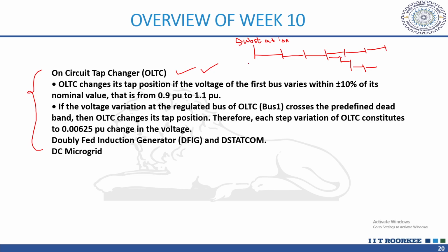Let's say my voltage here is 1.0 and at the far end is 0.97. If I increase the substation voltage to 1.1, it will be reflected at the farthest end, not linearly. I am representing it linearly here, but the idea is that as you vary the substation voltage, the same is reflected throughout this radial structure.